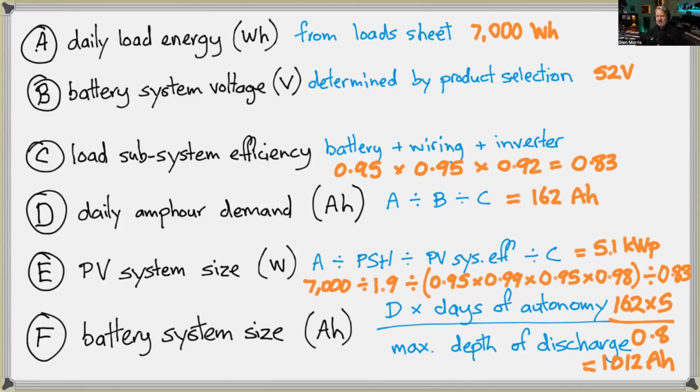And in the case of inverters, battery inverters have a slightly lower efficiency than solar inverters because they've got a more difficult job to do. Generally, in the case of this one, it's a 52 volt battery trying to make 240 volts, so it's doing a big voltage and current transformation. Also, it tends to have a large transformer in it, so there's some transformer losses. And it's generally running, on average, at a lower power level. If you look at the load in a home, you don't have it running at full power all day long, as opposed to a solar inverter on a sunny day, which is running at full power for hours on end. So solar inverters often run at very efficient power levels.